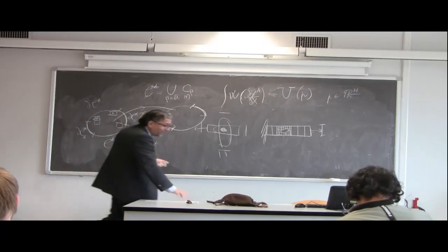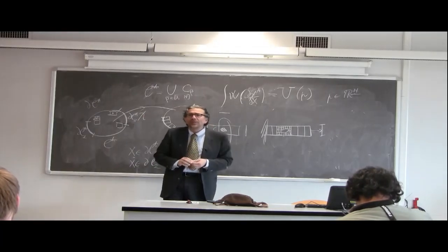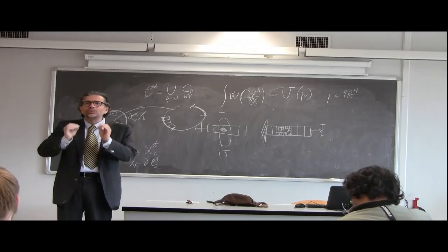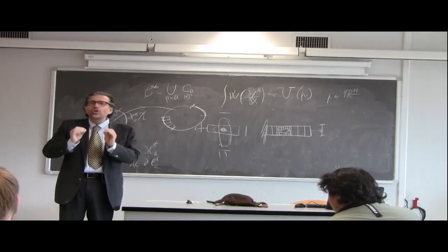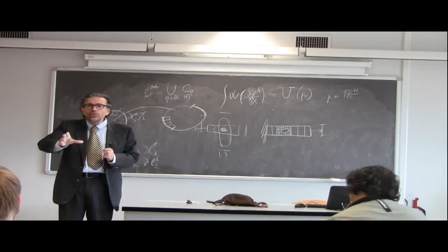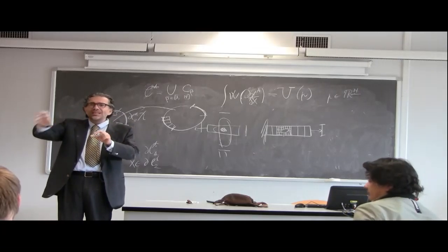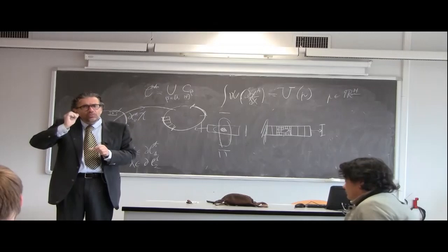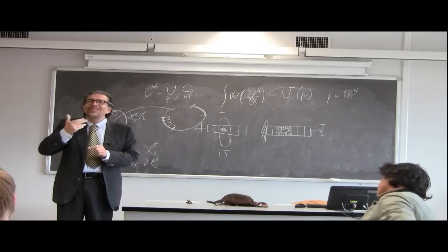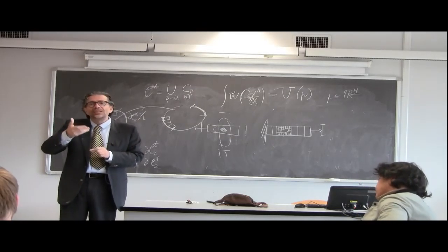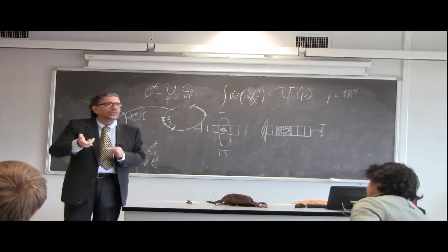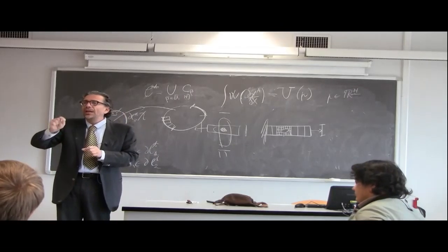Now, what is very nice and beautiful in COMSOL is that it was the first software which allows you to drive your choices, to decide what you want to do. So it allows you to choose a refined mesh here, a less refined mesh there. Do you know that you want a Lagrange polynomial of 4th order because you have a reason for expecting that you need better gluing of derivatives? It allows you to do it automatically. You click on it and you get it.